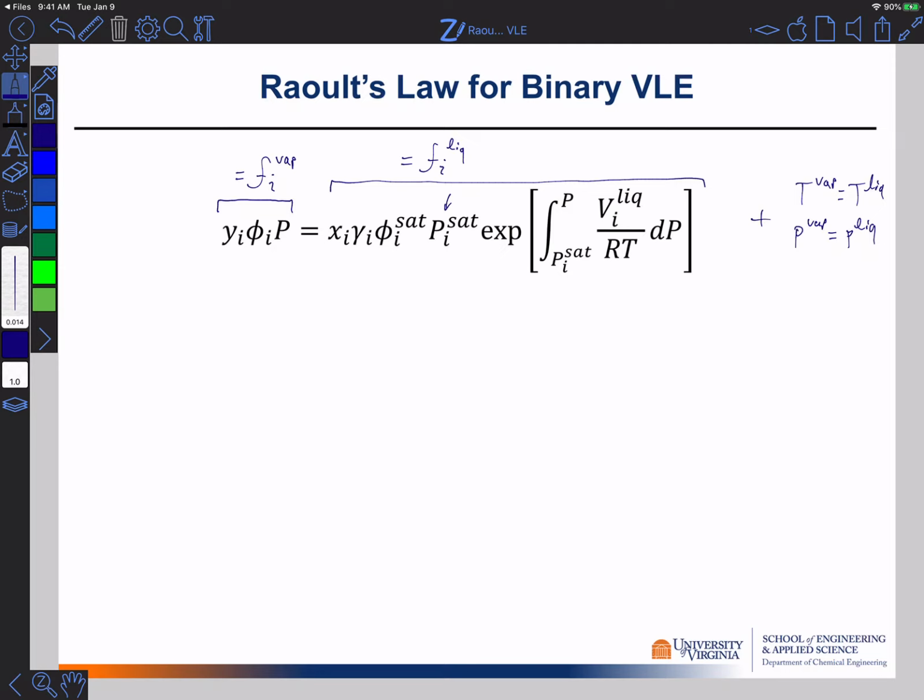Now, in the first part of the course, we're going to drill down to ideal VLE. We've talked a little bit about the ideal gas and the ideal solution ideas so far. And we've talked about the fact that Raoult's law is used to describe equilibrium, or this equality of fugacities of a component across the phases in equilibrium with one another, in situations where the vapor is an ideal gas and the liquid phase is an ideal solution.